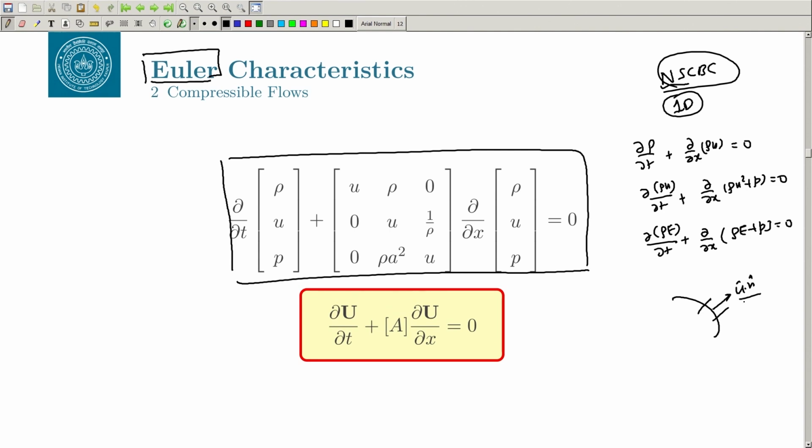Okay, so as we saw, that gives you whether it is inflow or outflow. So, we will be basically interested in u perpendicular, and then you can make a local 1D assumption there and implement all these equations. So, if you expand it, this will become dρ/dt + ρ du/dx + u ∂ρ/∂x = 0, which is what is written here.